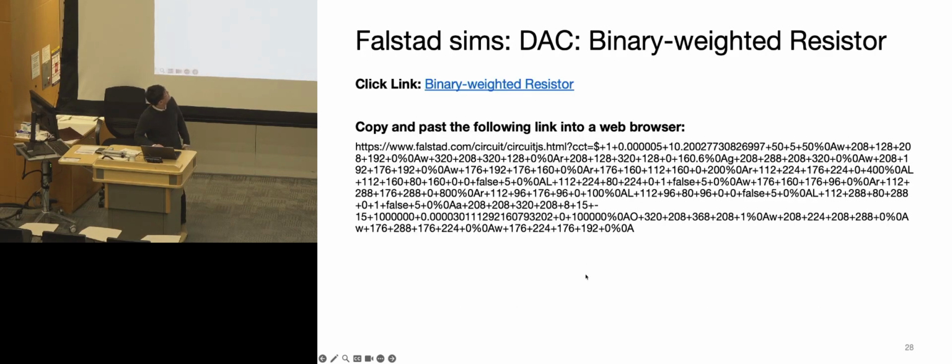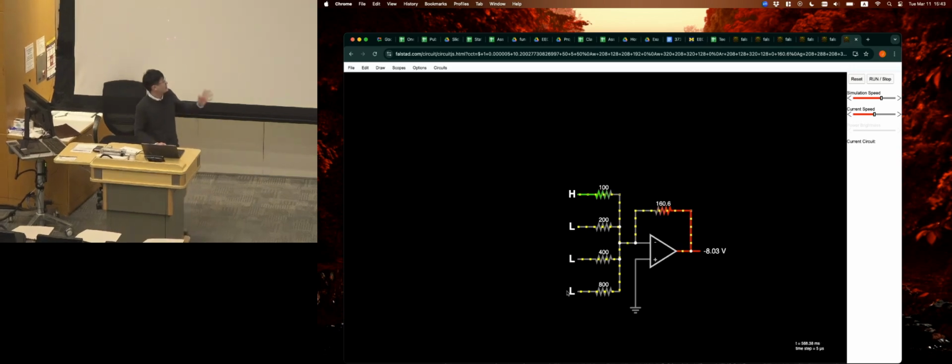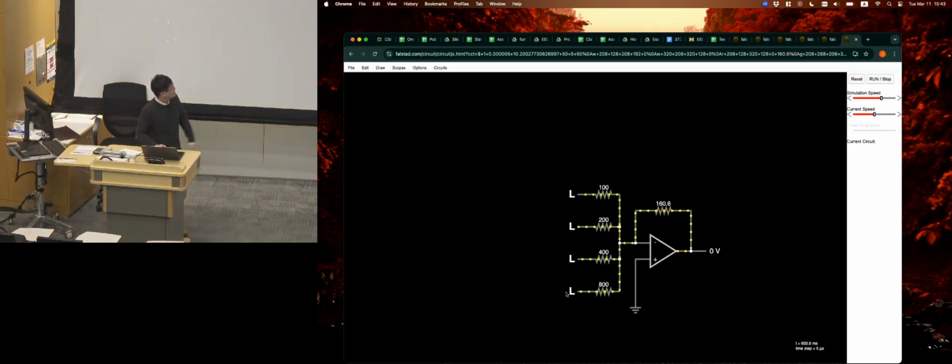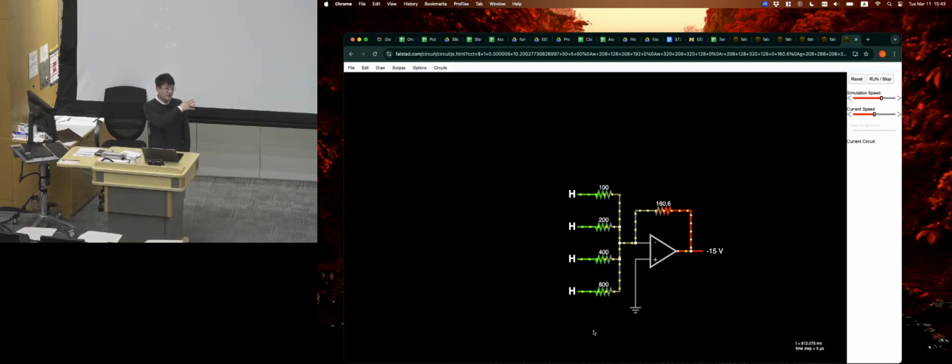And of course, we're going to have another demonstration here. This one is pretty straightforward. It starts with 0, and then when you turn on 1 bit, you get 1 volt, and then when you turn one more on it is 2 volt, and if you go all the way, it's essentially 15 volt. It's again a 4-bit DAC, and each step is 1 volt as before. The advantage of this one is that from a circuit building perspective it is simpler because it uses even fewer resistors. Previously we used 2 times n plus 1 for n bits. This is basically just n plus 1.